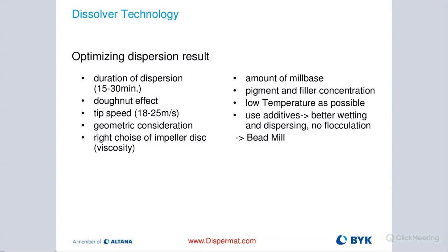Fill rate about 50%. That's what we're aiming for in the container. Anything more than that, you're probably going to spill. I mean, you can go up to about 70%. It's still okay, but not any higher than that. Really not recommended. You can go as low as 40% fill rate. That's fine. Don't go any lower, then it makes it a little bit more difficult to oscillate and find the sweet spot inside of the container, right? So try to stick with about 50% fill rate. That's ideal.